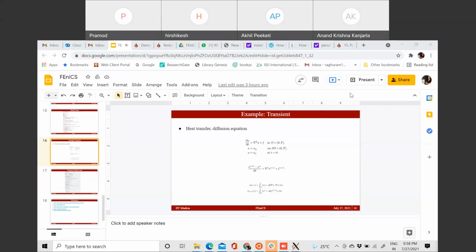I'm also working with phase field, but don't you do something like a delamination then, extra on top of that, or you just say that phase field works for everything? No, actually, no delamination. We say it in fracture terms, but in phase field we have just 2 phases. So once it fails, it will be 1. In terms of fracture mechanics, we say delamination along the interface, but here we don't need to track it.